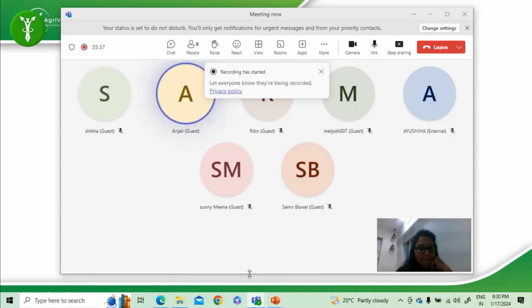Ma'am, because there is nothing given about distance or surface temperature. Just directly temperature is given, and if we calculate the Biot number, it's very less than 1. So we can use this lumped capacitance method to solve this.